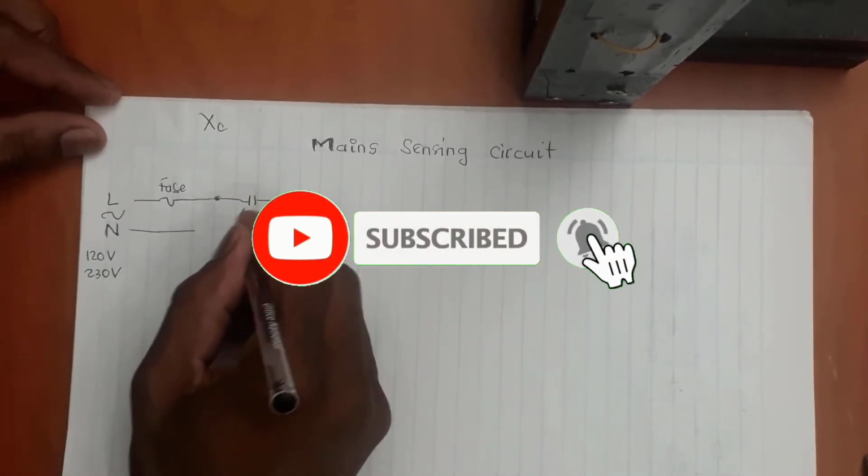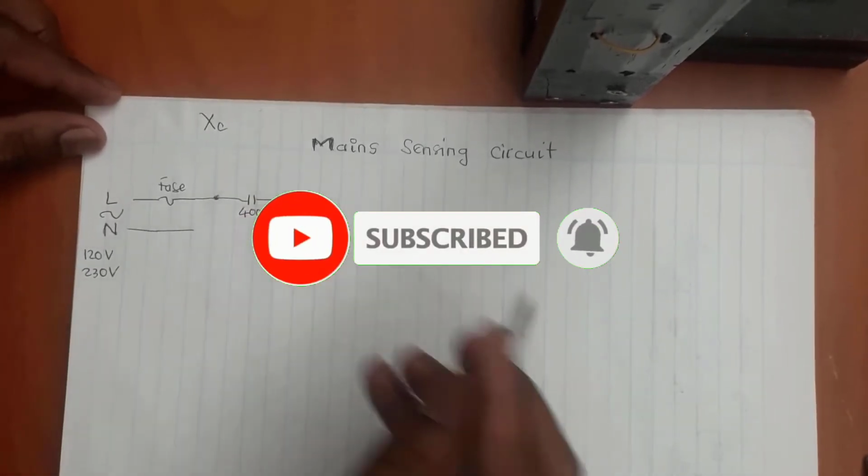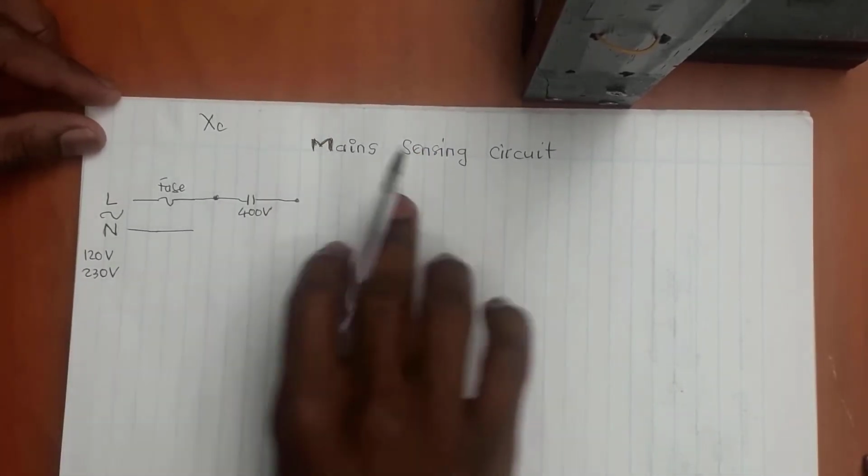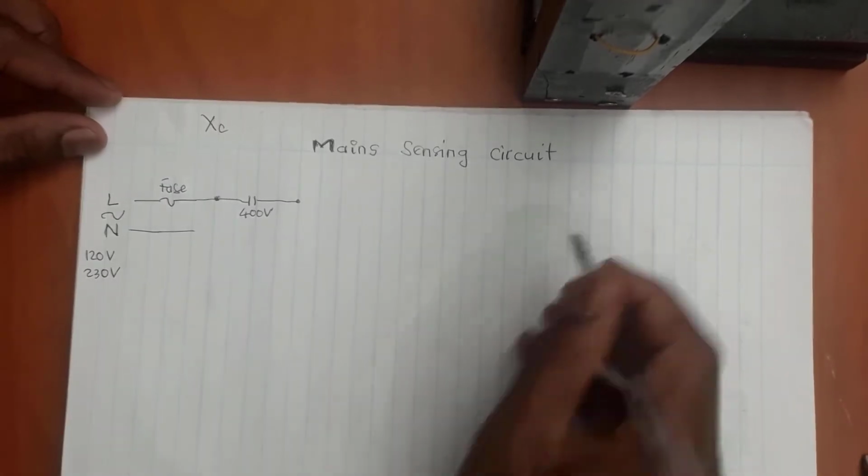Now, remember this capacitor here needs to be a 400 volt capacitor, okay? Now the value of the capacitor will determine how much current will go into our load circuit that we want to have on this side, okay?